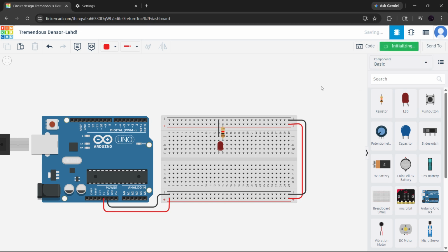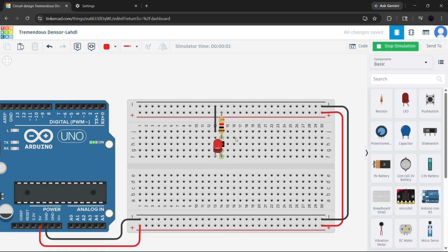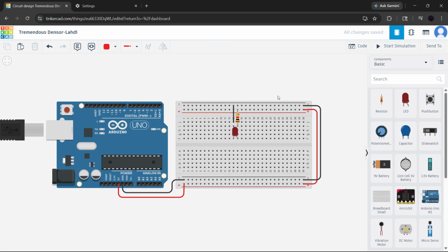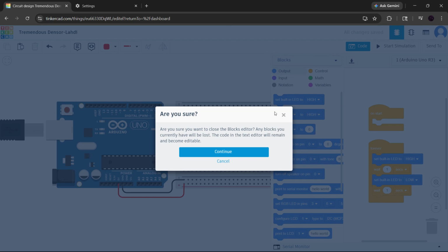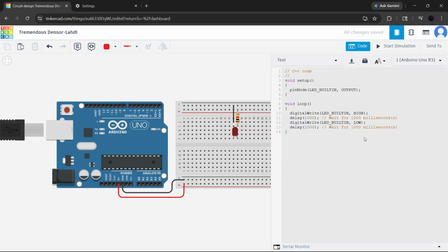Now let's move on to code, because if you are using Codeblocks or Arduino inside Tinkercad, the problem may be in the script rather than the wiring. Look for infinite loops or overly aggressive code that runs without any delay. If your program is constantly executing too fast, it can freeze the browser tab or overload the simulator. Also scan for syntax errors like missing semicolons, unclosed brackets, or red highlights in the editor. Those are often easy to miss, but they can prevent the simulation from starting properly.